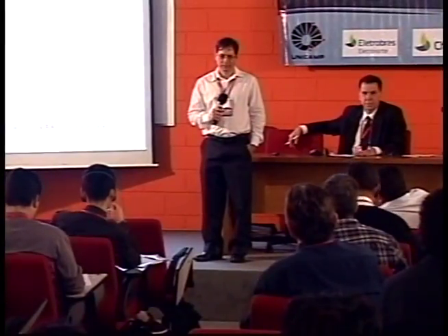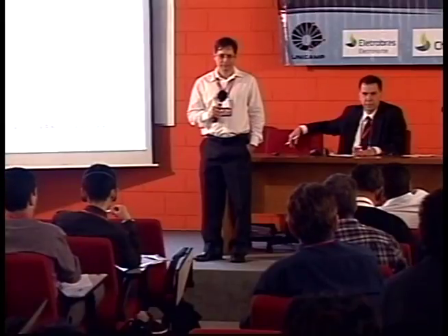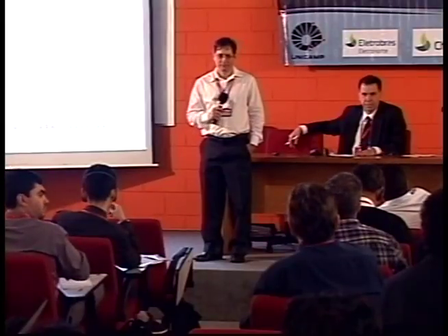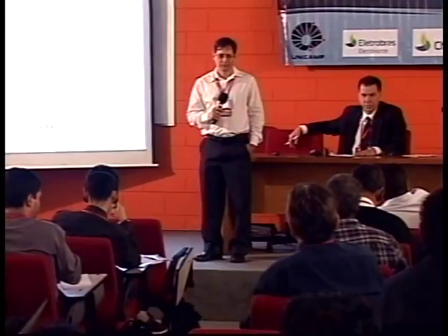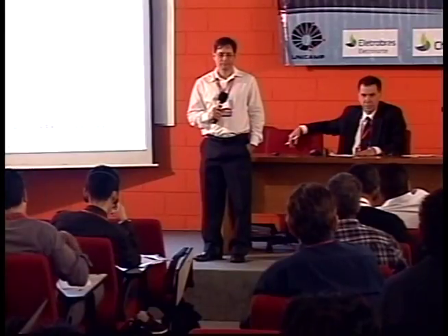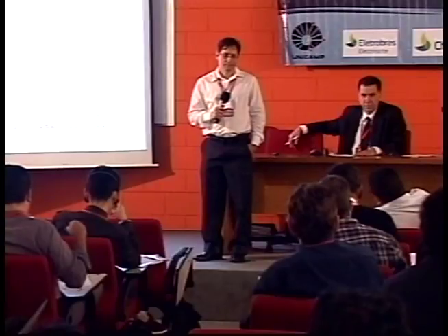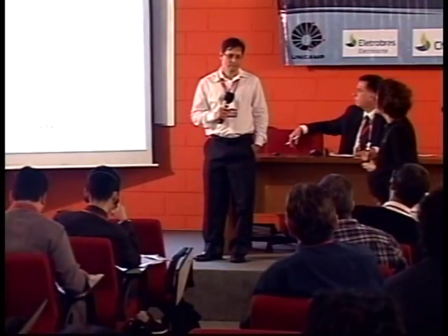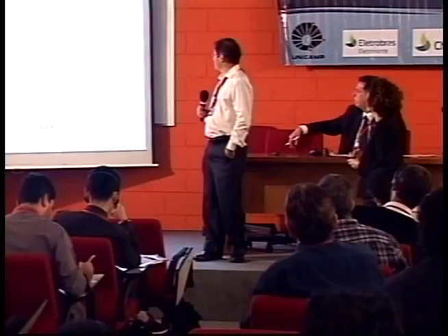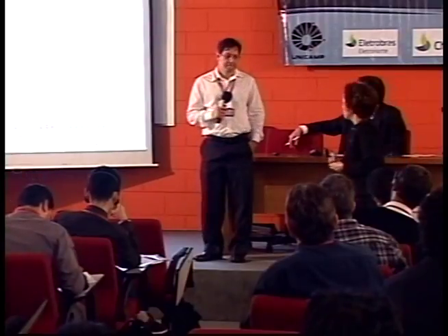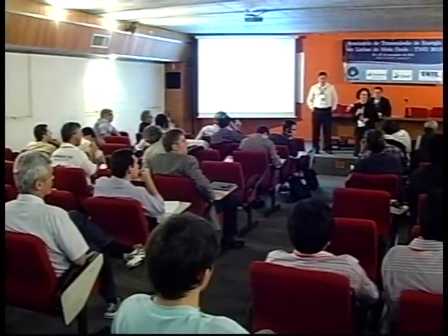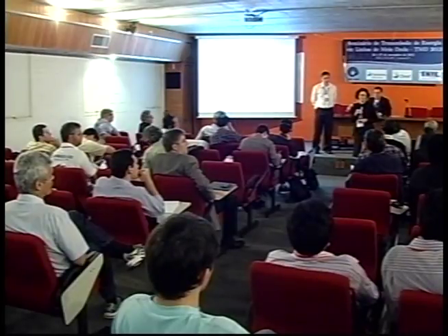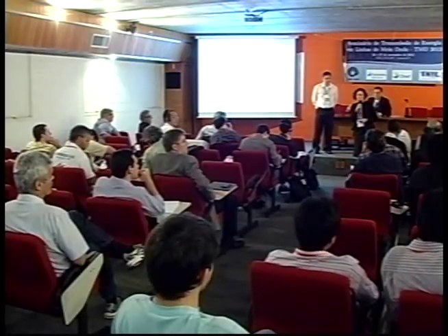So the impression I get, if we did not have the surge arresters, as both of you have mentioned, the overvoltages would be very high. So occasionally, this single phase fault would become a two-phase fault, because for sure there would be a discharge in the insulator chain on the phase C. Since the overvoltage, I believe the overvoltage would be high. And maybe, disagreeing with Vanderlei, this would become a three-phase fault even if there wasn't a plane crash. Let's forget about the plane.